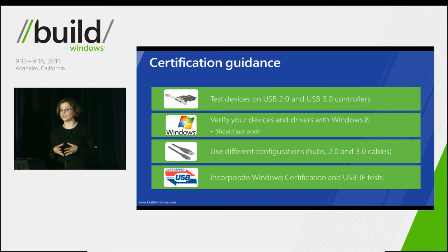Millions of PCs that are shipping today are offering USB 2 and USB 3 solutions. We call those mixed port solutions. And there are also millions of PCs offering just USB 2 that users have in their homes. As such, there's no guarantee that your USB 3 device will be connected to a USB 3 controller and a USB 3 port. So it is very important to test them behind both USB 2 and USB 3 controllers.